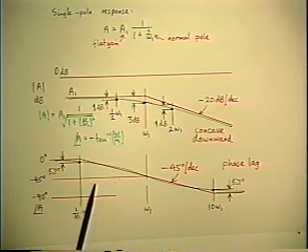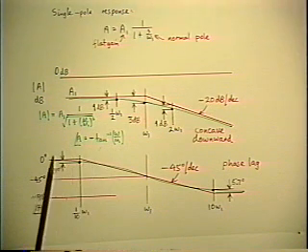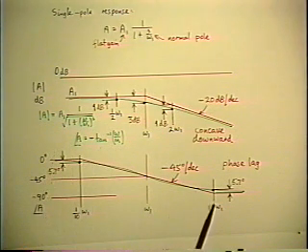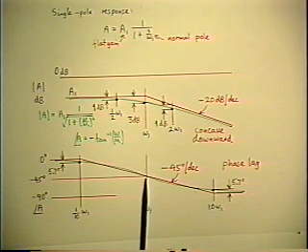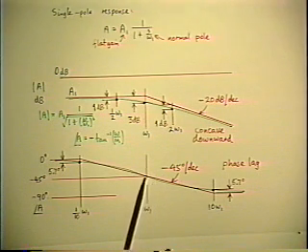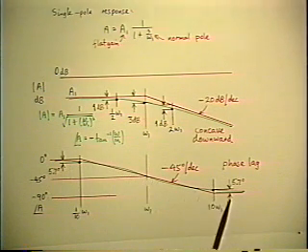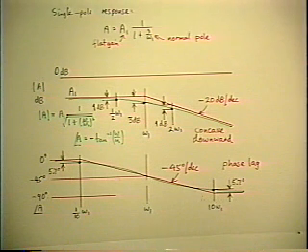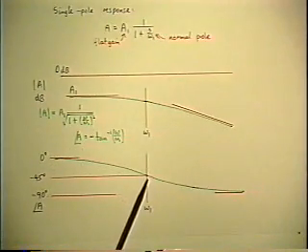So we're reduced now to actually plotting the function, the arctangent function. And we typically choose linear degrees versus log frequency. And again, interestingly enough, the function turns out to be antisymmetric around the corner frequency. That is, the shape of the curve, the green curve below the corner, is exactly the same as the shape above the corner, except reversed and inverted. So that much of the picture is what we have.